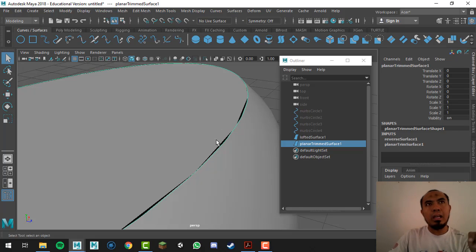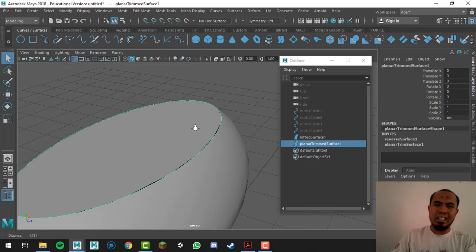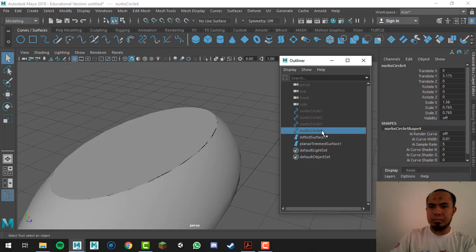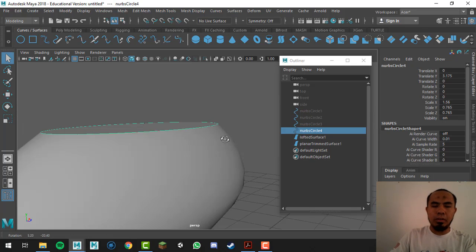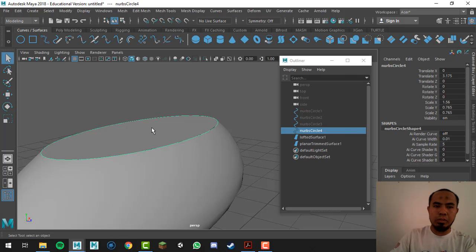So planar, as best as it tries to close that hole, doesn't really do a good job creating that cap. So it's good to know that we can use it for other reasons perhaps, but if you want to close a hole like this, maybe it won't work. Maybe you've got to trick or be clever with the way you do it. For instance, you could probably produce a rim in here.